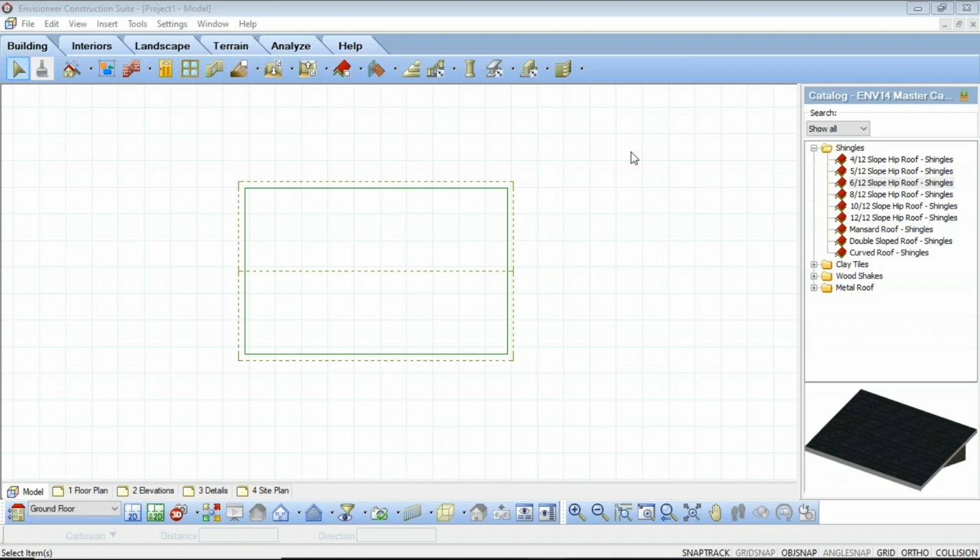So first we're going to look at roof rafter framing. Roofs have a framing configuration assigned to them that you see when you display framing. Framing can be displayed using the Display Framing tool and is included in the project estimates. Settings in the framing configurations let you specify whether or not you want each component in the roof frame to be displayed and quantified. You can assign a member type, usage, and phase to each member in the configuration.